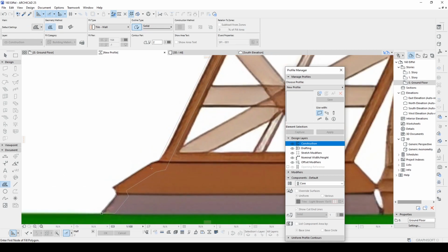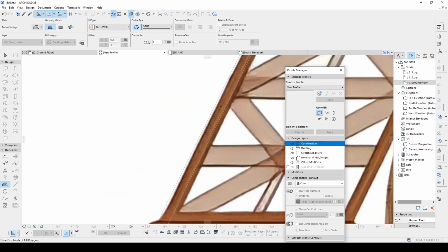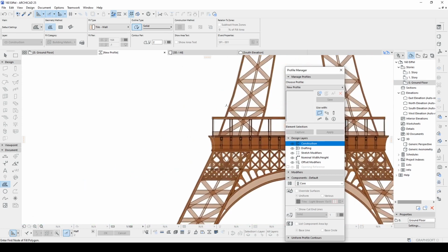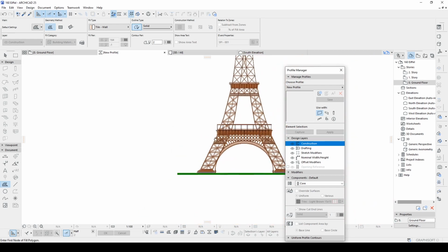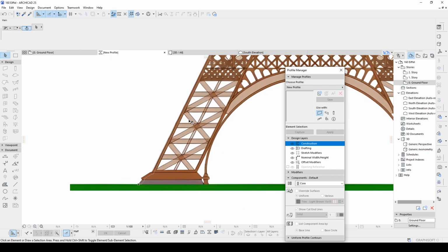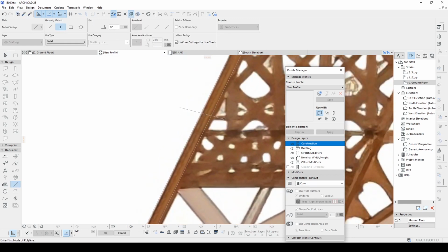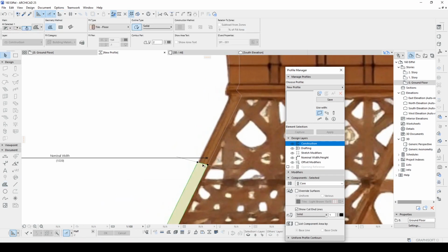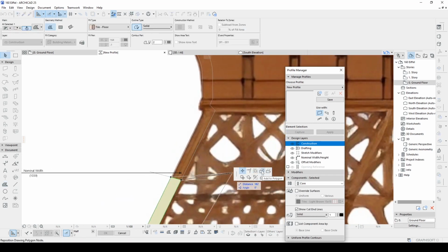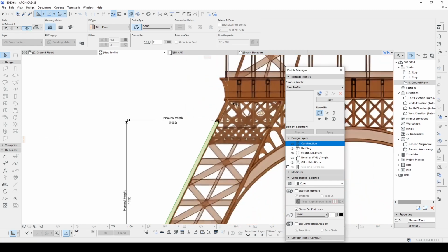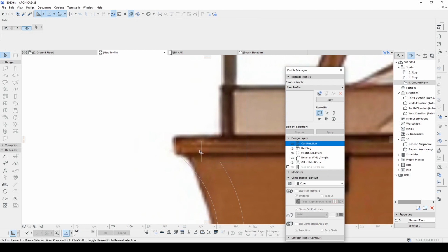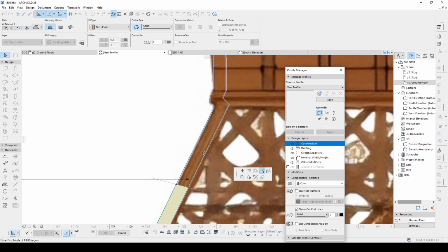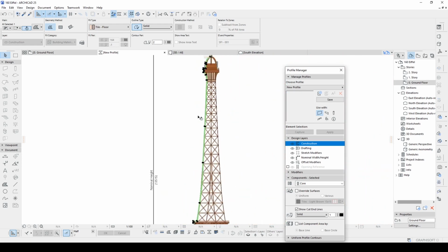Click the fill tool, hit the space and click the inside, and region not found around this point. Alright. Let's try again. Didn't happen. Okay. Once you get an error, something like this, you can divide your shape with your line and continue with partial filling, just like that. And after that, you are going to click your edge and hit add to polygon and continue. Yeah, there we have our problem maybe. Again. There we go.